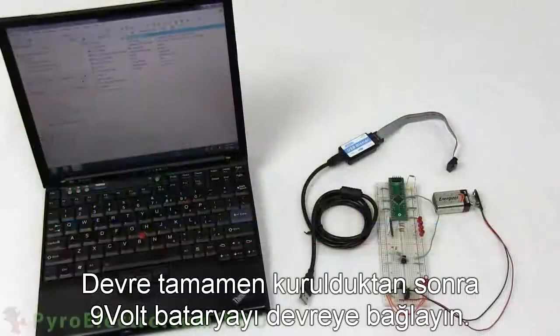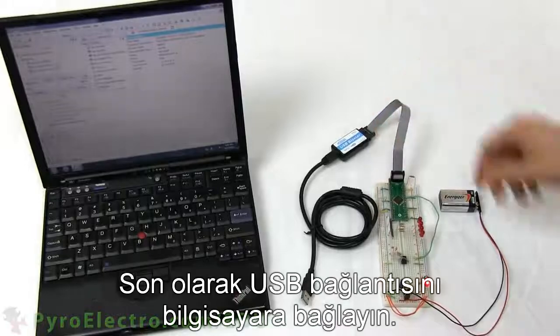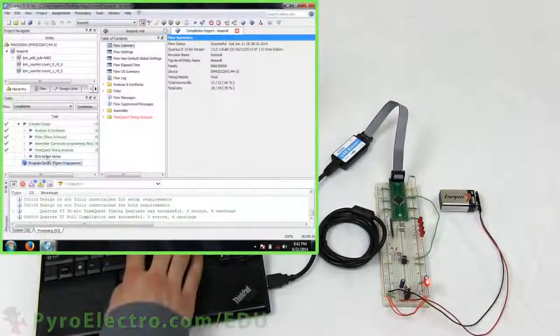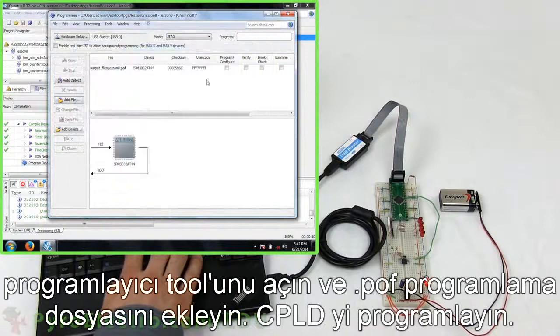And with the circuit completely built, connect the 9 volt battery to the circuit, as well as the JTAG programmer to the CPLD, and then finally the USB connection to the laptop computer. Open up Project 8 as we had it previously, and bring up the programmer tool. Add the .pof programming file, and then program the CPLD.